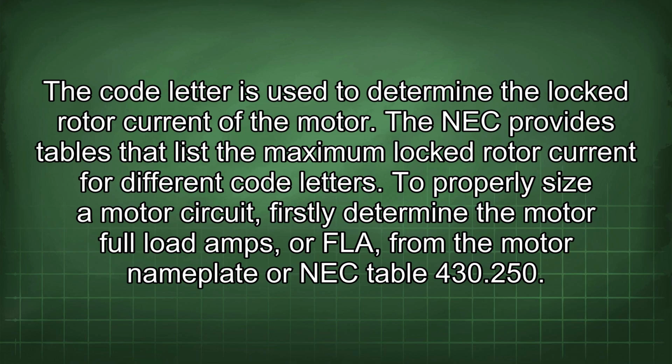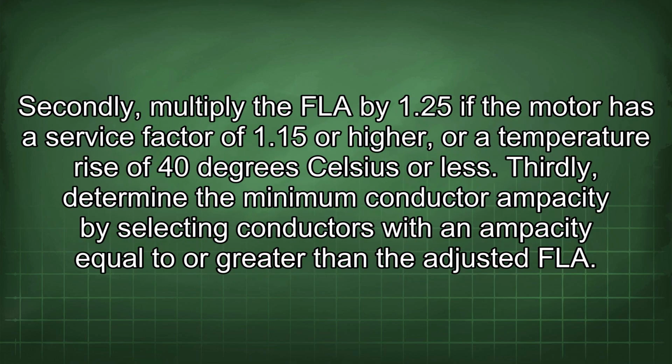To properly size a motor circuit, firstly determine the motor full load amps, or FLA, from the motor nameplate or NEC table 430.250. Secondly, multiply the FLA by 1.25 if the motor has a service factor of 1.15 or higher, or a temperature rise of 40 degrees Celsius or less. Thirdly, determine the minimum conductor ampacity by selecting conductors with an ampacity equal to or greater than the adjusted FLA.